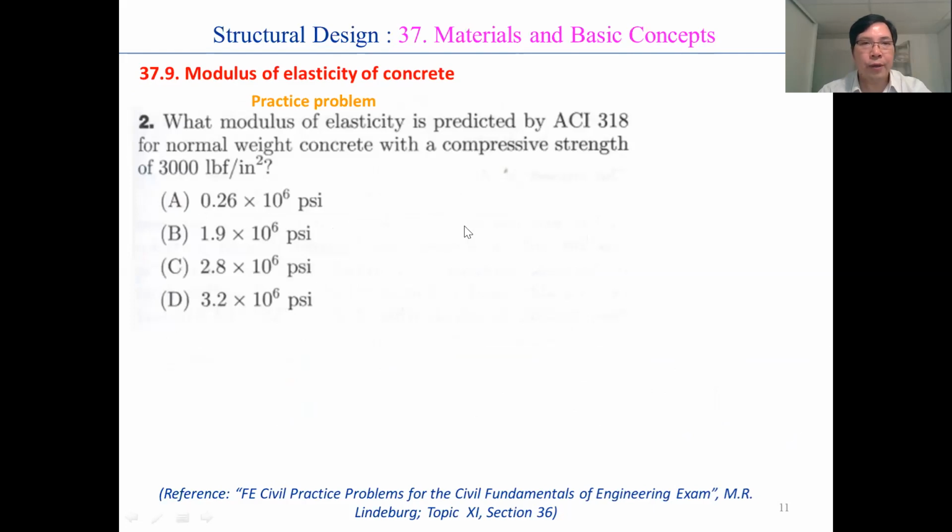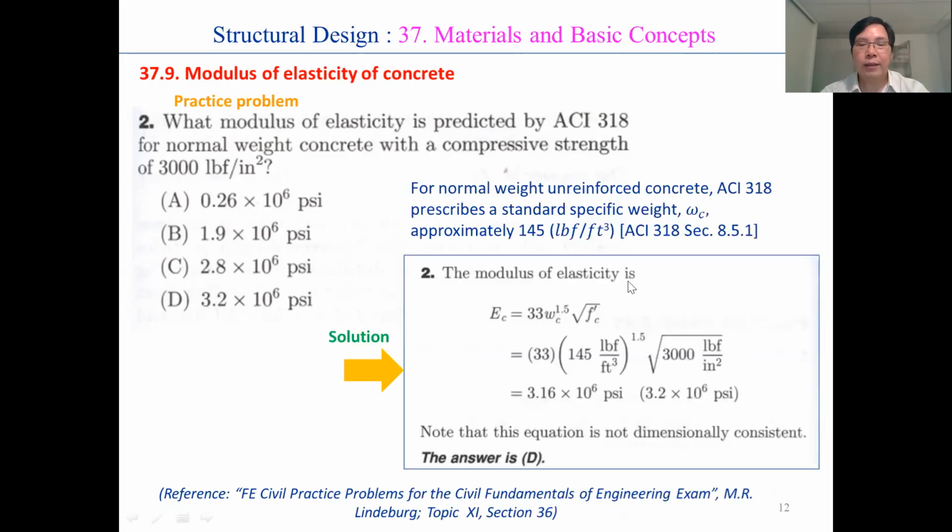And now I present to you in this slide the second practice problem. The question of this problem is: what modulus of elasticity is predicted for the normal weight concrete with a compressive strength of 3000 lbf per square inch? And you can see the corresponding equation that I presented to you before.